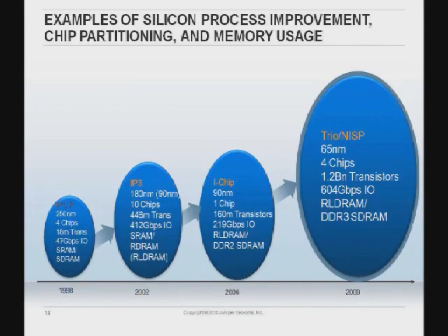And then we did Internet Processor 3, released in about 2002, fabricated using a 180 nanometer process. The 90 in parentheses I'll talk about later. In this system there are 10 chips per PFE, and these are 20 gig PFEs. The main reason to split the chips in that case was memory bandwidth. Of all those 10 chips, 5 interface to memories, data memories and queuing memories.